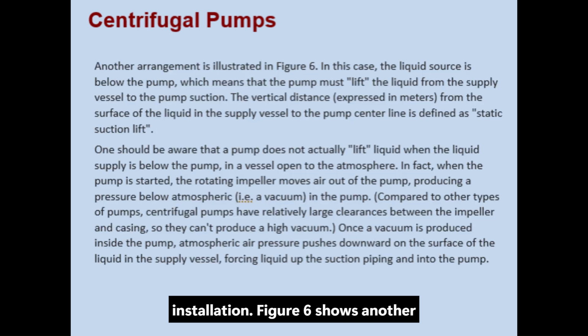Figure 6 shows another important arrangement where the liquid source is below the pump. In this case, the pump must effectively lift the liquid from the supply vessel. The vertical distance from the liquid surface in the supply vessel to the pump centerline is defined as the static suction lift.